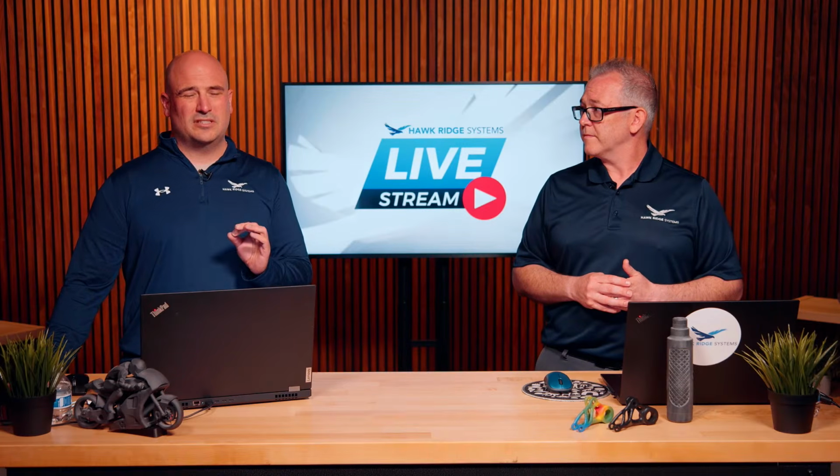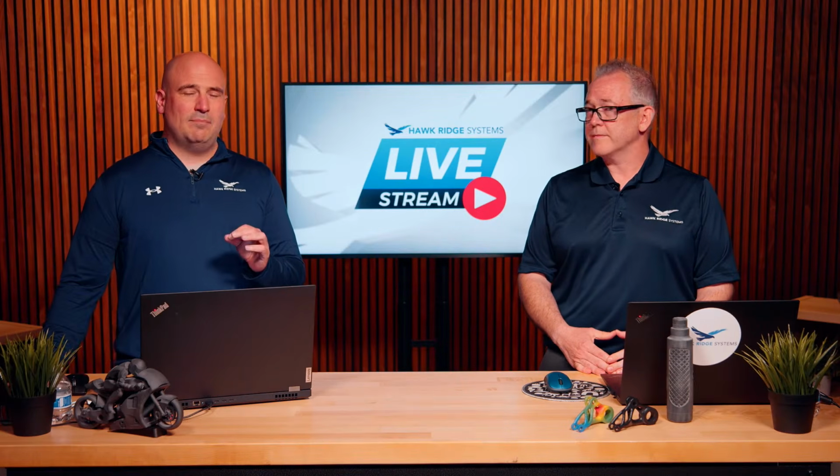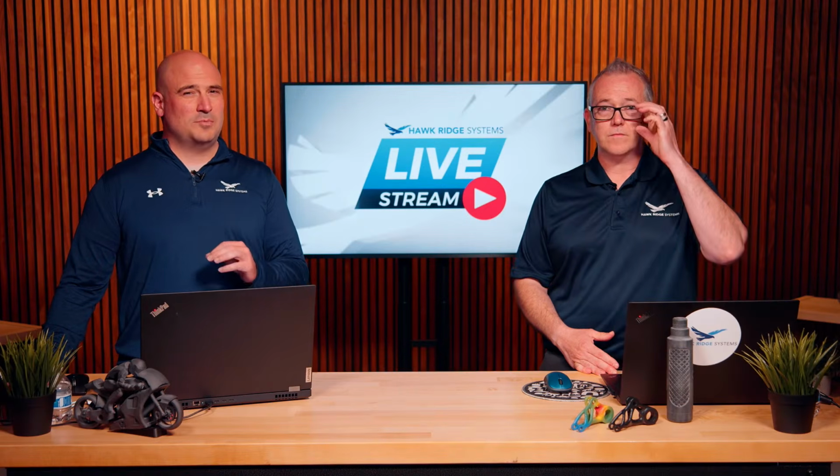So what it's going to do is default to lightweight mode. A lot of people have seen the feather on the icons for their assembly tree, and lightweight means that it's only the bodies and the graphics and not the features. Unless you expand it, then the feather goes away. That's going to be loaded into your current memory. The thing you have to understand is that lightweight mode is very good for the individual features and the components, but it is not affecting the mates or the different assembly level features. So lightweight mode is a very good start. It's where most people are going to live day in and day out.